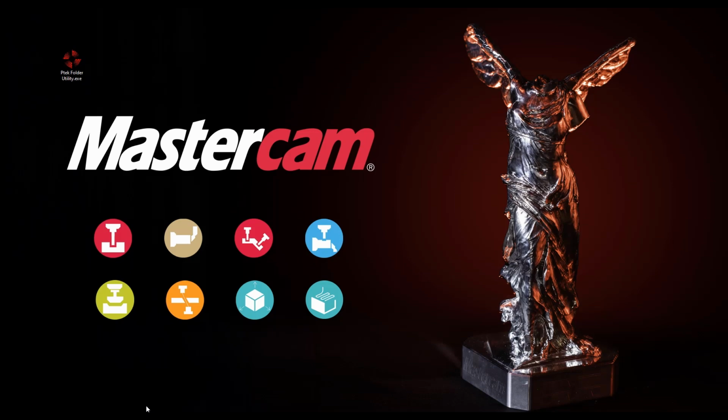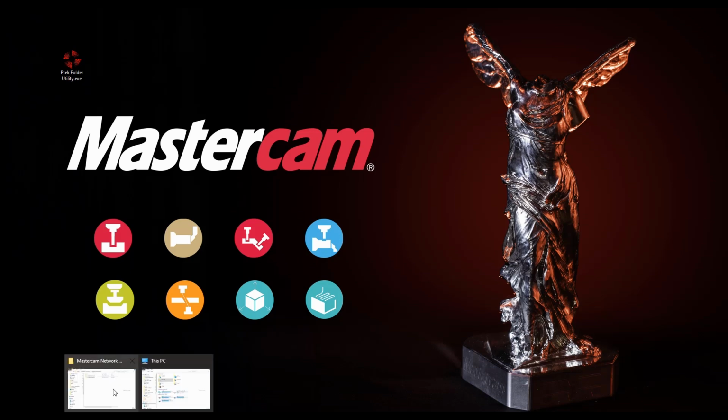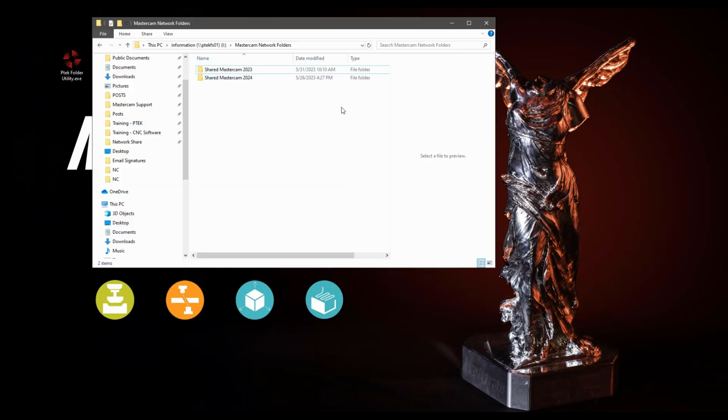First, you need to select a network location to put the share on. Ideally, this is a location that every user has read-write access to. Minimum, we need read access. I've chosen this network location. Next, you want to make sure that you have your Mastercam up and running and working the way you want, because we're going to take one user's folder and use that as the starting point on the network.